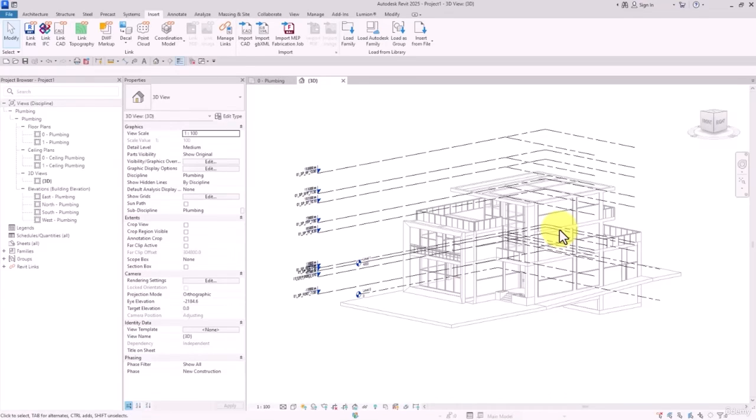Remember, guys, if you are working as a team member in a large Revit project, it is quite necessary for all the members to have a common base point. This way, you could actually prevent so many possible future problems. So again, in a large project with different disciplines, it is quite crucial for all the members to have a common base point.